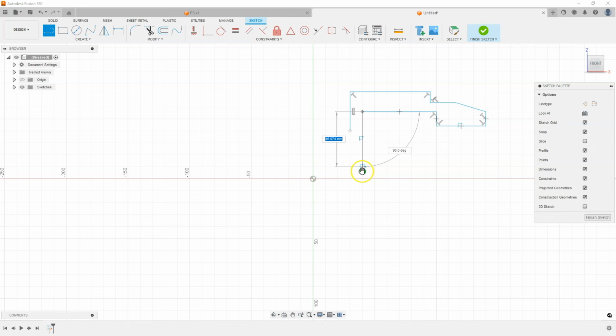Okay, let's finish the line drawing command, and in a moment we will connect these points together, but the line drawing command is still active, so draw the line that coincides with the x-axis. Okay, press escape to cancel the line drawing command, and now grab this point and move it near to this point. Okay, and select these 2 points with the Ctrl key and select coincident constraint. Okay, the shape doesn't have to be exactly the same, it is important that it is similar.